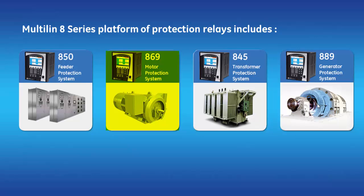869 relay has been designed for protection, control, and management of medium and large induction and synchronous motors. 869 relay offers a powerful solution for critical motor protection applications with an advanced thermal model and voltage-dependent curves for high inertia loads. 869 implements many ease-of-use features such as single screen setup for faster motor configuration and startup, and a motor health report providing detailed motor diagnostics, enabling quick and easy identification of motor issues.